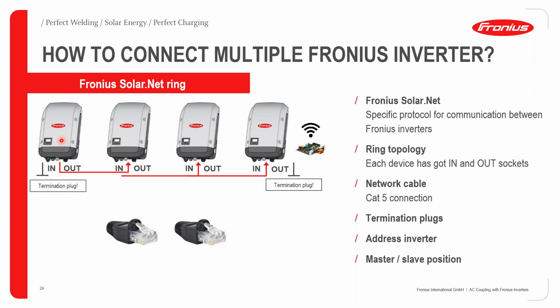And then for each inverter, you also need to configure a unique inverter number. That is very, very important, so that the master inverter is able to communicate with each of these inverters, and each inverter serves as an address for the SolarNet ring.